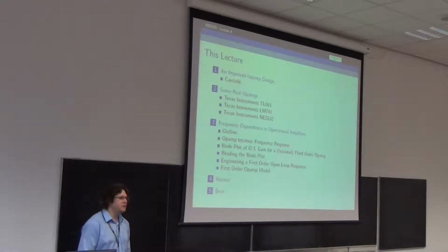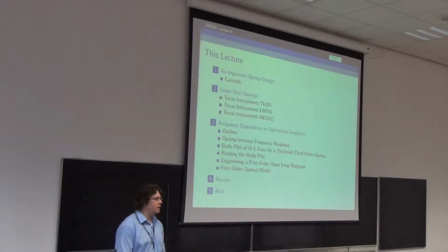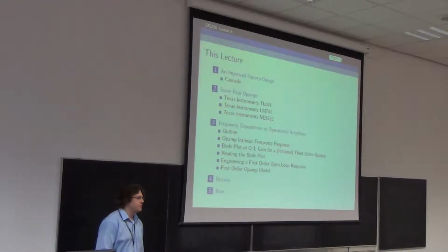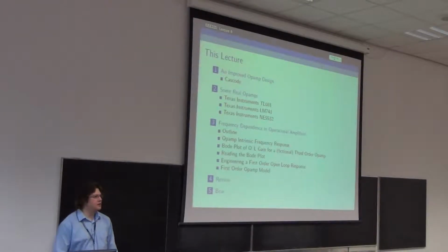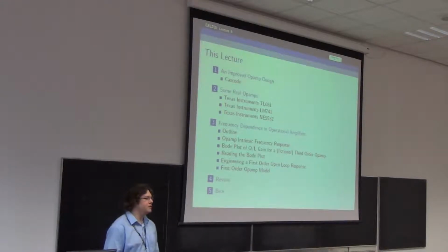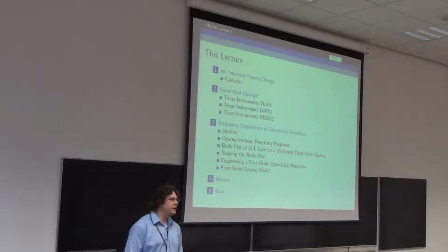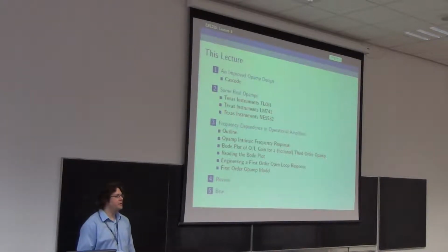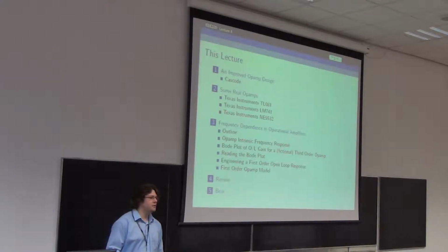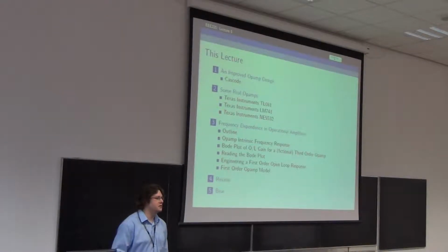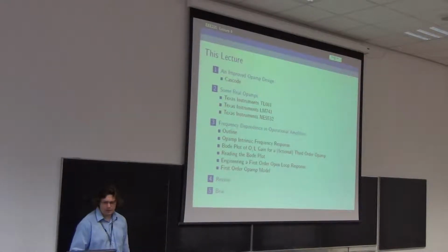Even the op-amp circuits that you see in the data sheets of the op-amp aren't the real circuits, they're still simplified. Generally speaking, the manufacturers will not give away their schematic diagram. Even if they did, they wouldn't be giving away their IP, because you don't know what dimensions the transistors are that they're making on the chip, and you don't know what the chip's actually made from. You don't know the doping densities and so on and so forth. You don't know the characteristics of the individual transistors.